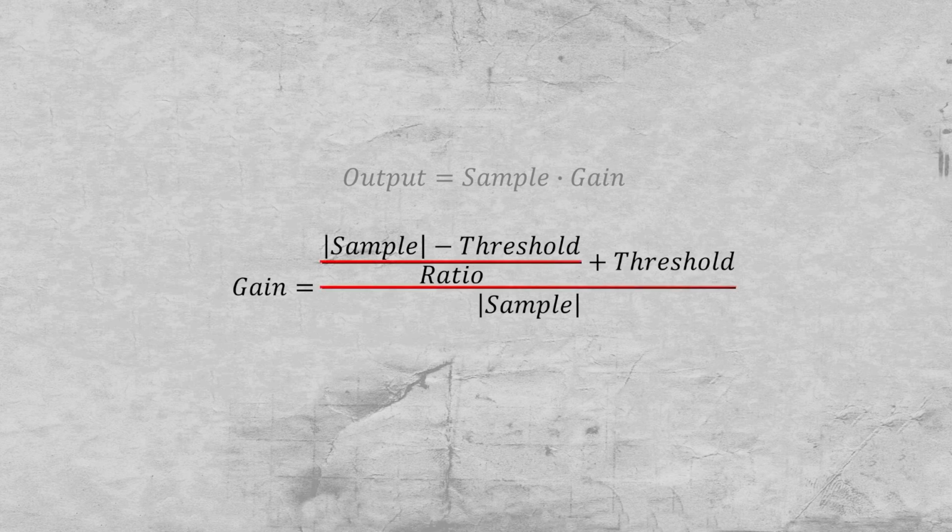We need a total of 2 divisions. However, divisions, unlike multiplications, are considerably more complex to implement in FPGAs and have no hardware support in smaller devices like our Cyclone 10. However, if we only set the ratio of the compression in ranges of 1/2, 1/4, 1/8 and so on, we can use simple bit shifting to the right here and can remove one of the 2 divisions. But to calculate the actual gain, we still have to divide in order to obtain a sufficiently good resolution.